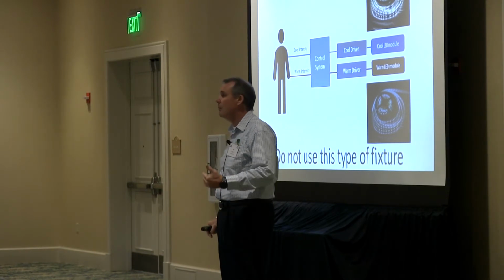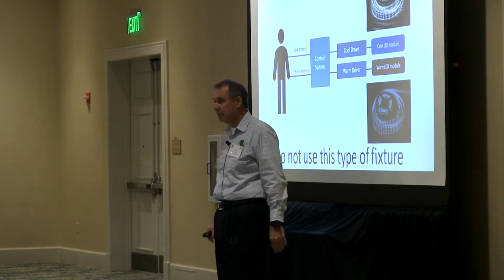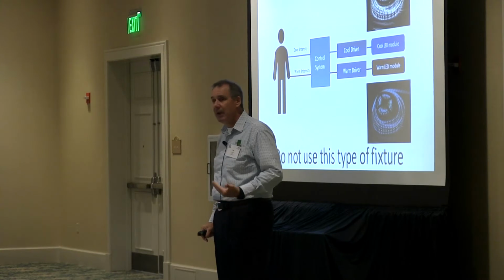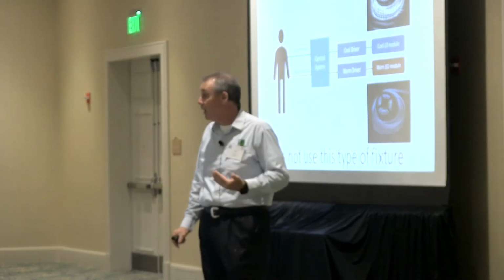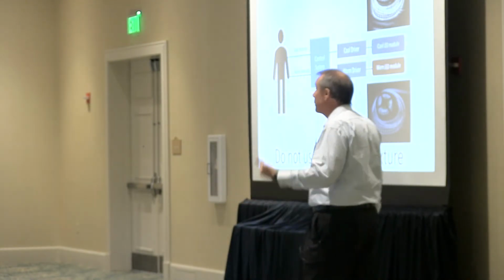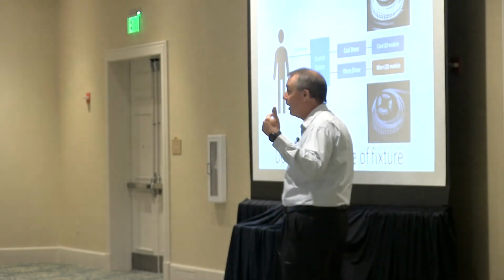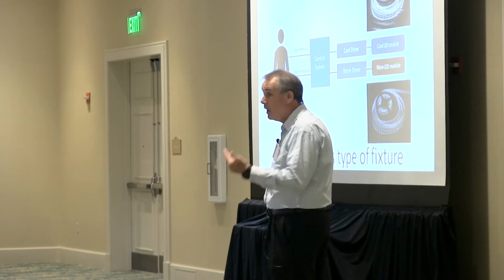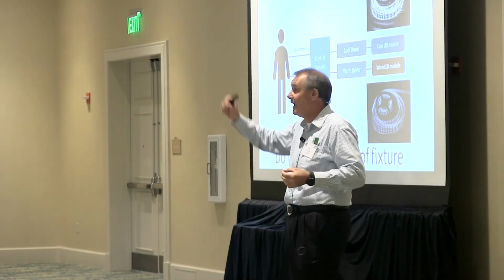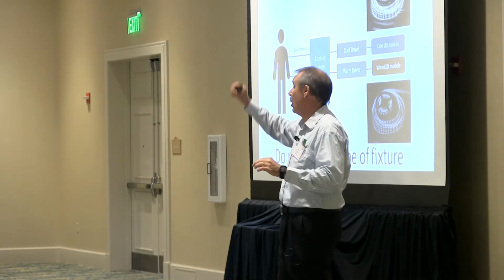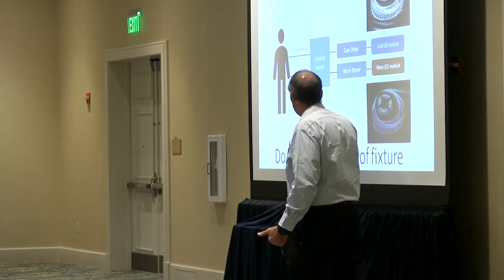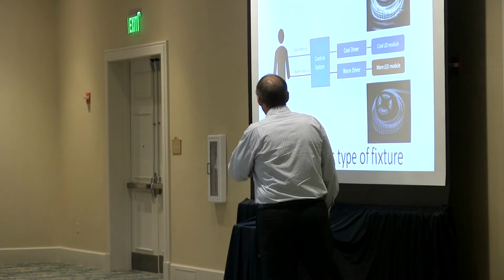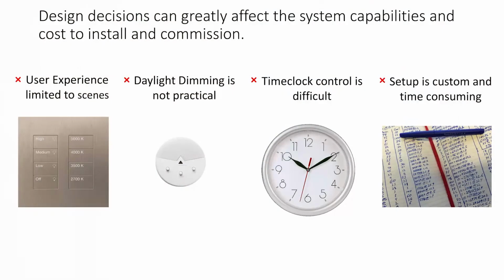It is not practical to use in the real world. On paper, it looks like I can do it, but commissioning it, I can't do it. I can't program scenes. I can't do daylight control. I can't do time clock fade rates because I don't know what it's going to fade to between two points. It looks easy, but don't use it. If you don't believe me, try it.